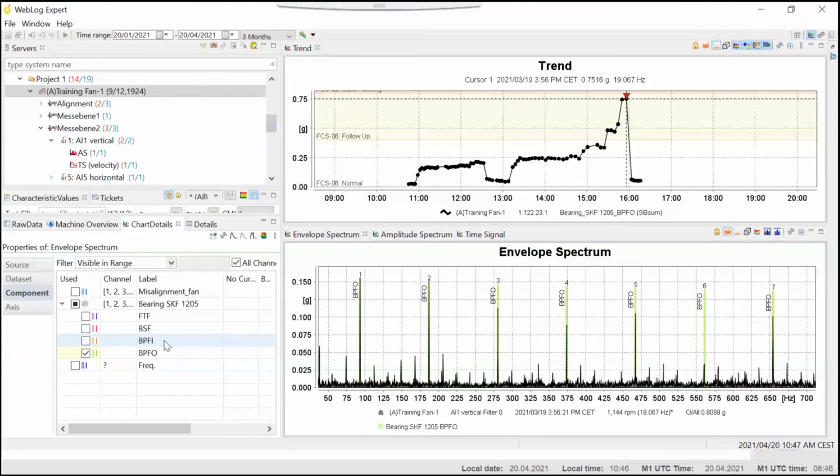That's right, yes. You would be able to say, oh, that's probably a bearing fault, but you wouldn't be able to say which bearing it was unless you had a list of the defect frequencies. So it's much easier after we've done this post-processing to extract those frequencies and compare them with a list of what we have as likely candidates.